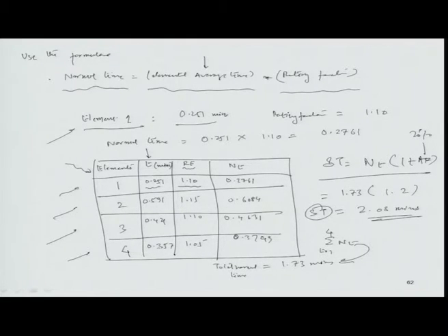So, an operation comprised of 4 different task elements, which have individual components of their normal times based on the operator efficiency, the average operator efficiency is mapped in terms of the standard time which I finally assign to this particular set of 4 elements constituting one particular job. So, that is how we do the time study.